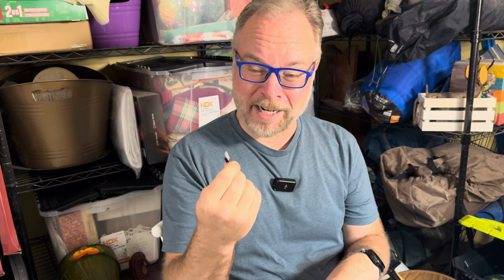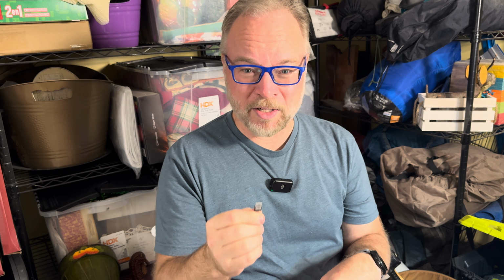It's got a little tiny heat sink, and then you can screw this into a much larger heat sink. So this can actually take quite a lot of current through it and can switch significant amounts of amperage. It is an N-channel MOSFET, and what that means is that you have to drive the gate voltage high in order to get the MOSFET to conduct.